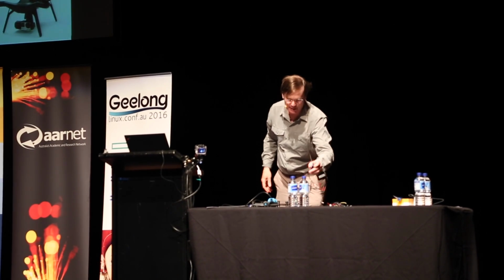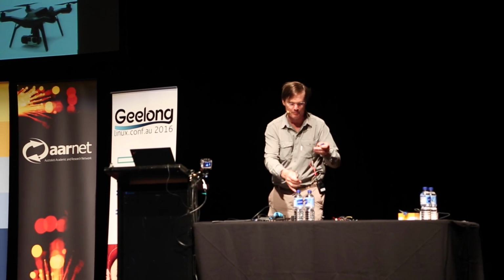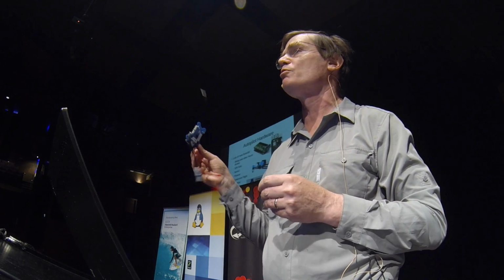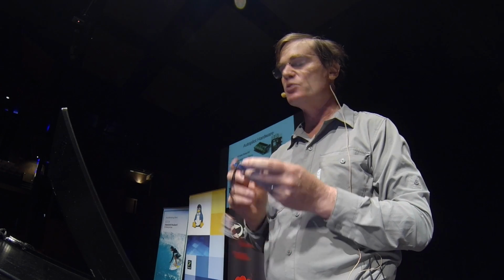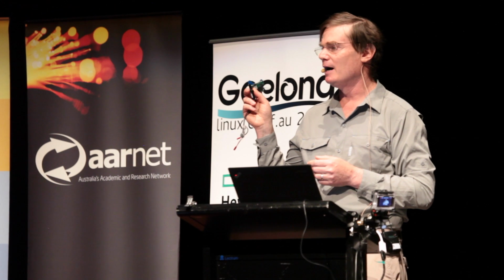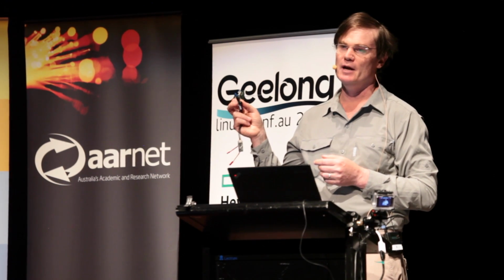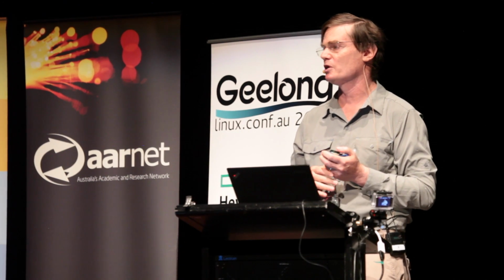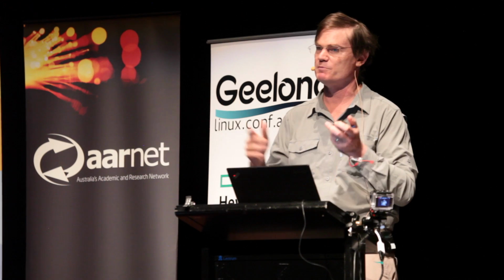Another very interesting one lately is this one. This is the Qualcomm flight board, which is a Snapdragon CPU, and Qualcomm's pushing this quite hard as the future of autopilots. And it is a wonderful piece of hardware. 4 ARM Krait CPUs plus 3 DSPs. And the DSPs have a complete shared memory with the ARM CPUs. So all of the memory is shared, with their own L1, L2 cache, but all the rest of memory shared.